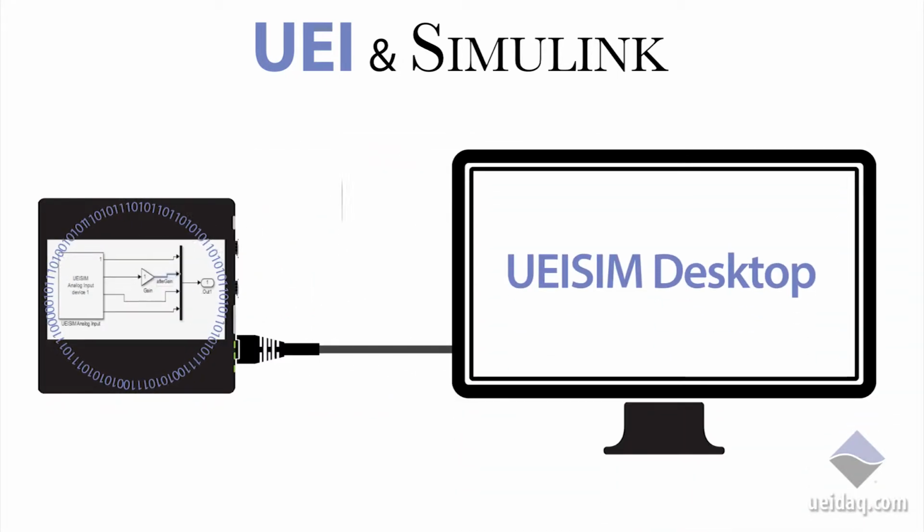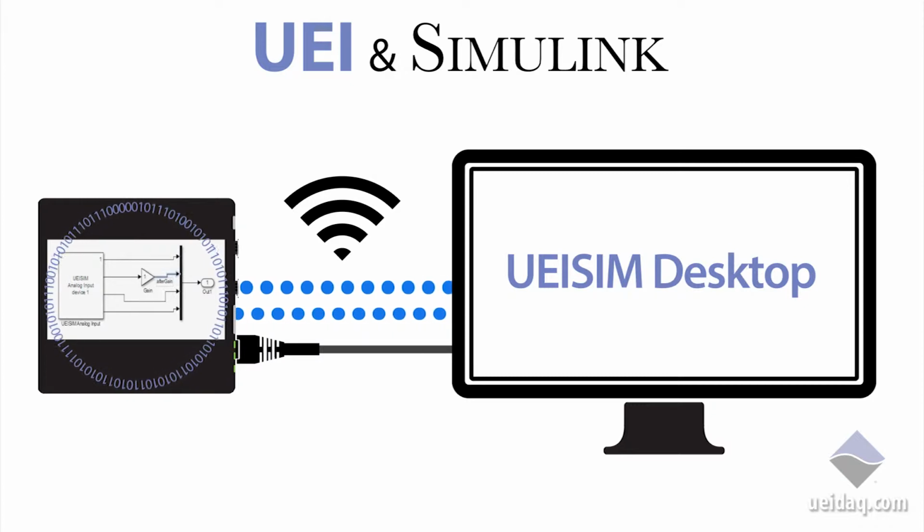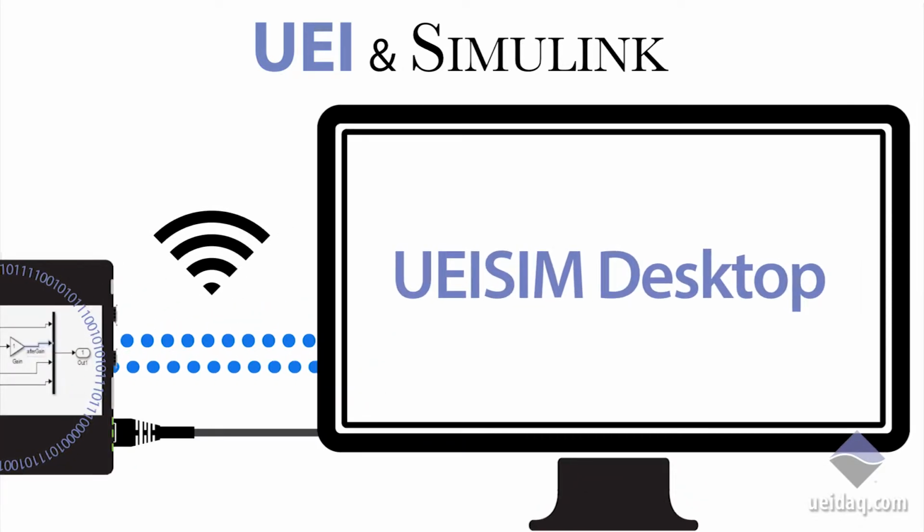The UEI Sim Desktop was developed to allow you to remotely manage your Simulink model, be it monitor the model, or change the model's parameters at runtime. This decouples your Simulink model from the MathWorks environment. We have created a shared variable framework over industry standard WebSockets or TCP/IP. The UEI Shared Variable Framework server is running alongside the model on the embedded hardware.